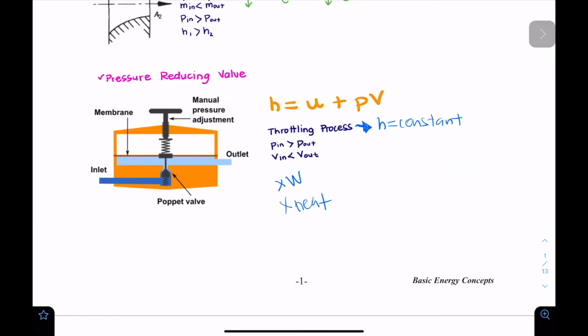Okay, so throttling the flow is going to cause a significant reduction in pressure, because a throttling device causes a local pressure loss. Basically, throttling can be achieved simply by introducing a restriction into a line through which a liquid flows. So here, let's say we have it completely open, and we start putting a restriction into the flow that goes through here. That's basically what it's doing.